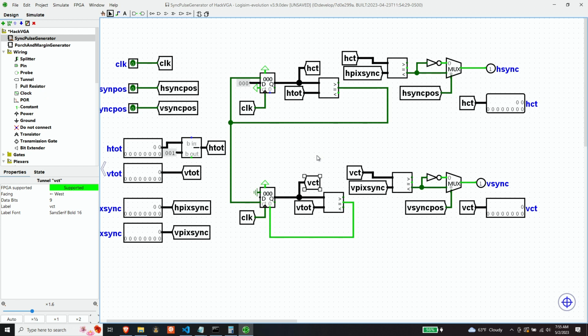And the solution that I have in here works, but it's frankly ugly and it always bothered me the way I did it. So it occurred to me a more straightforward solution. So I'm going to go ahead and implement it and talk about it because it just was obvious after I did this. When the horizontal counter gets equal to the horizontal total, we're actually one past the pixel that is valid for the horizontal line.